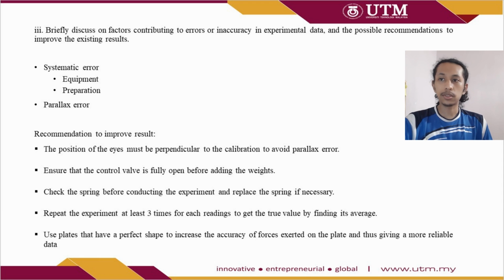For example, the control valve may not be fully open, which will affect the result and cause the reading to be slightly off, or the spring that we use may lose its elasticity, and it can cause the reading to be all wrong.